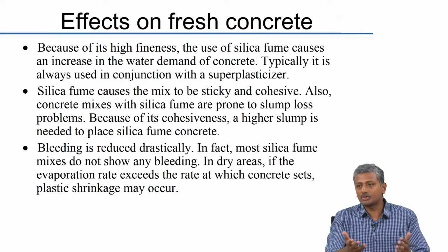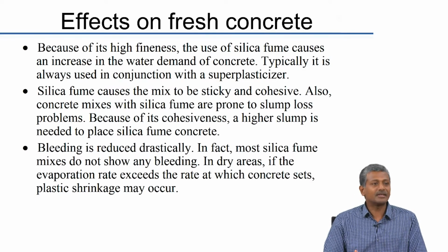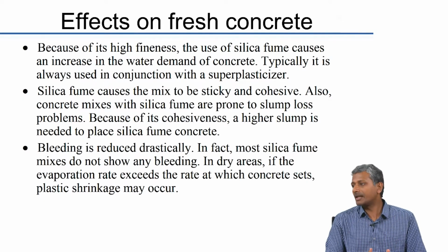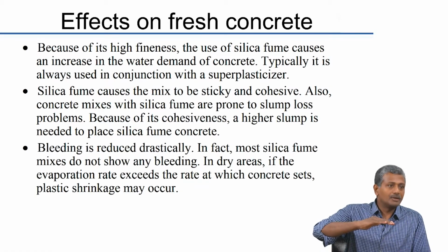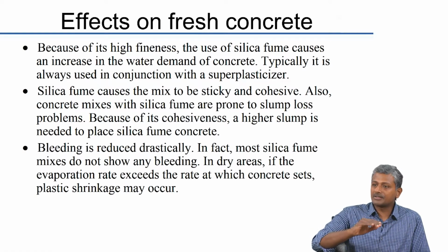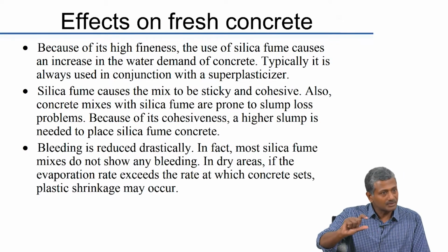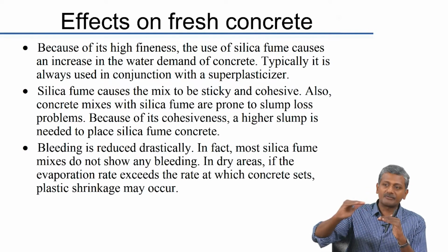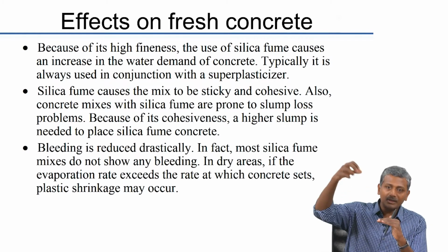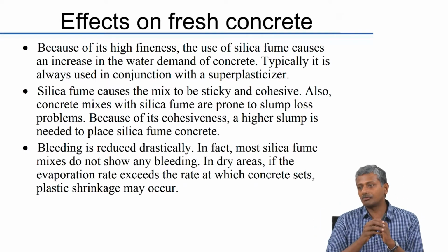Now, I am not saying concrete should bleed because of that, but I am just saying that in situ concrete, when we typically cast it, especially in horizontal elements like slabs or beams, there is a rise of water to the top. Okay. The detrimental part of that is obviously that this water is going to increase the local water to cement ratio at the cover concrete zone, but the advantageous part is that when this water comes up to the surface, it prevents the atmospheric drying of the internal water from the concrete.